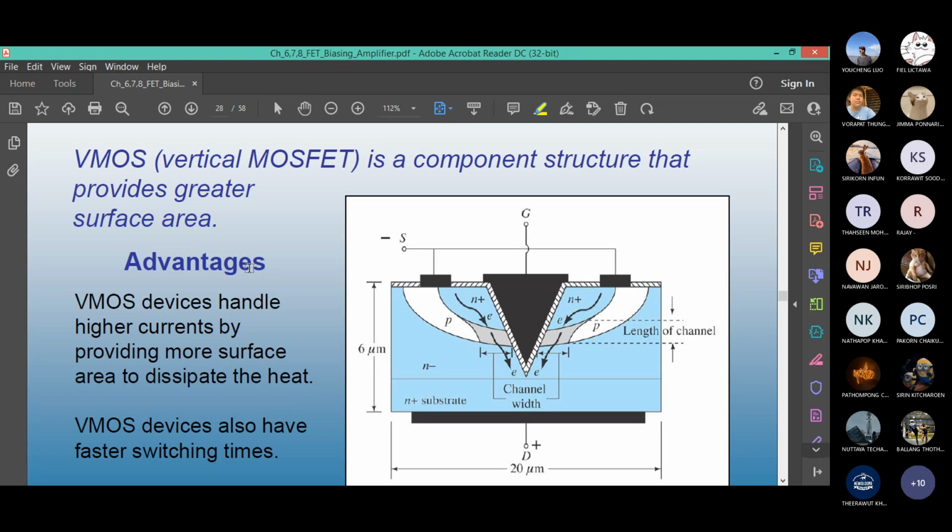The lack of an electron we call a hole, instead of calling it a proton. So more particles participating means more current conduction. Remember, the JFET or MOSFET, the field effect transistor, is a unipolar device. Not both electron and hole participate, either electron or hole, depending on what type of substrate you have. For the BJT, it's bipolar. Electron and hole both participate in current conduction.